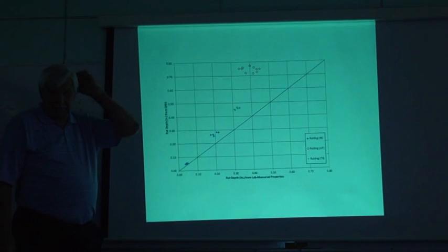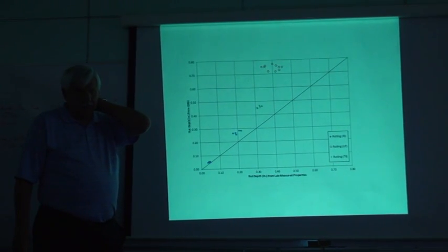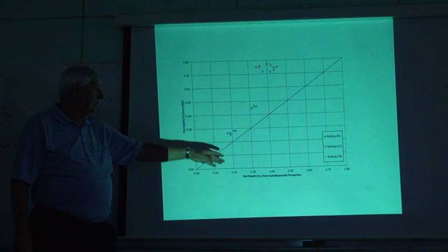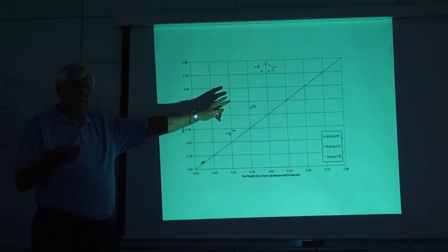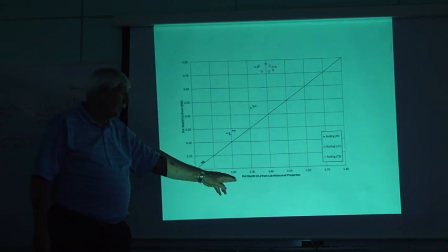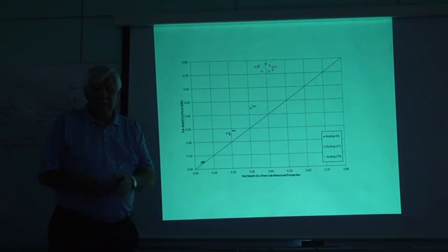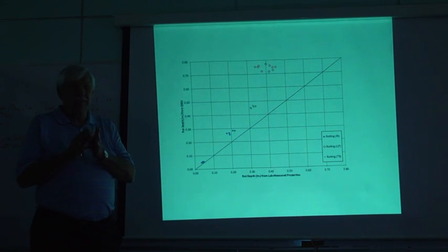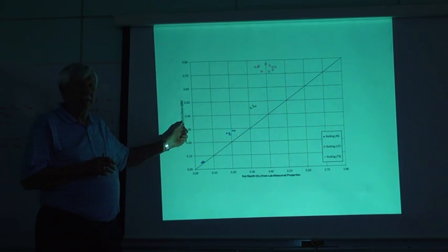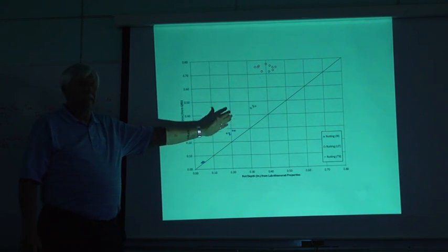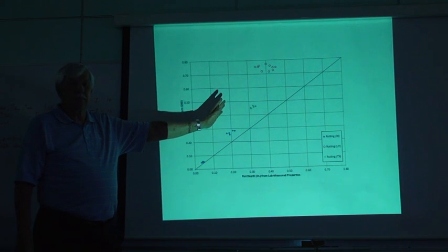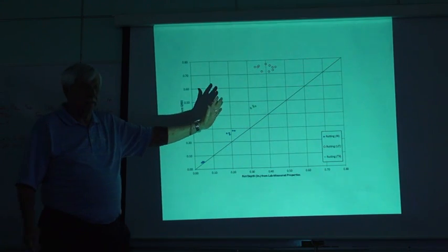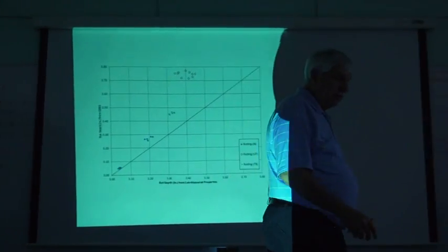But what this result did show us, and this was just analyzed here about a month and a half ago, is that there were subtle differences in the computational techniques used in the computer program that uses the measured E* compared to the MEPDG. So this problem can be easily corrected, will be corrected, but it just goes to show you that we're still on the drawing boards with this thing and got to do it fresh. However, everything else I'll quickly show you.